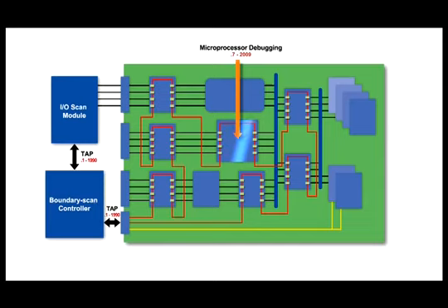For devices like microprocessors, it may be desirable to control the power consumption of the debug logic or to quickly access a specific IP block on a system-on-chip device to improve the software debugging performance. This additional functionality is defined in IEEE standard 1149.7 and can be accessed through the JTAG port, or, alternatively, through a reduced pin count TAP defined in .7.